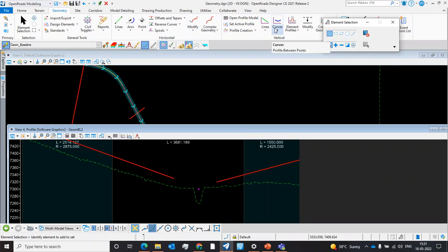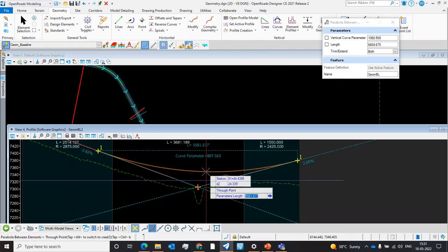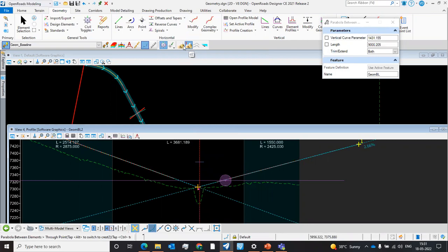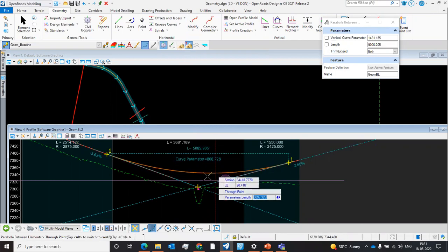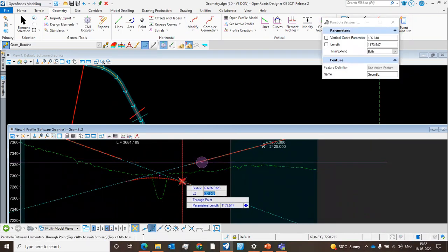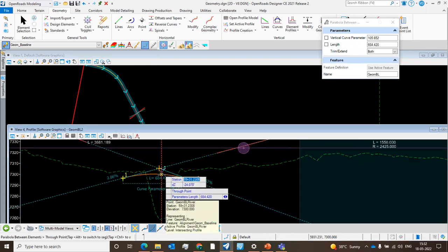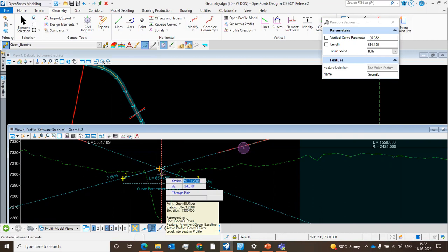Now we'll provide a curve between elements, simple parabolic curve. Nothing is there with my cursor. It's asked me to select first point, then second element. Now you can see with my cursor, there is a station and DZ, because I have chosen DZ from here. If I want a delta Z, I want to create a delta ground for this profile. So as I told you, using tab key, you can move up and down. So as I move in station, I'll select this as my reference point.